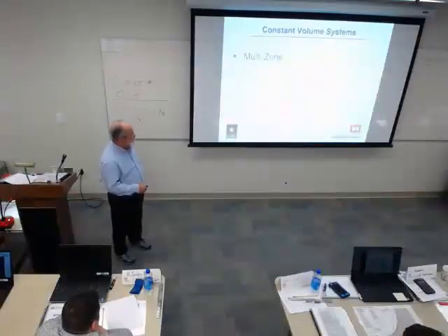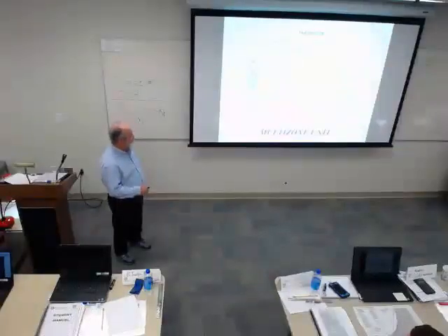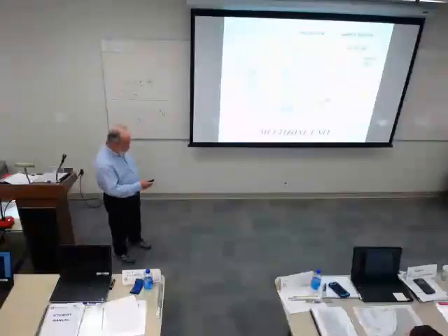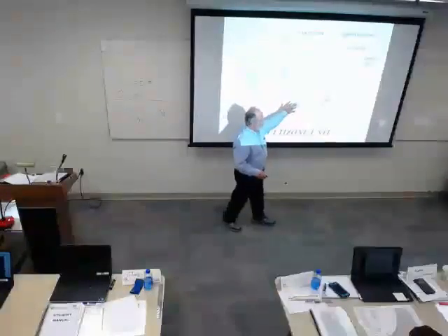Okay, what kinds do we have? We don't see many of those anymore, although I hear they're coming back. We're going to see it. That has a fan section, hot deck, cold deck. We mix air coming off each of these, coming into a duct that goes outside.